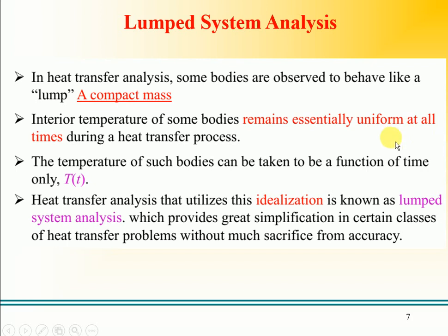The interior temperature of some bodies remains essentially uniform at all times during a heat transfer process. The temperature of such bodies can be taken to be a function of time only, not a function of position.